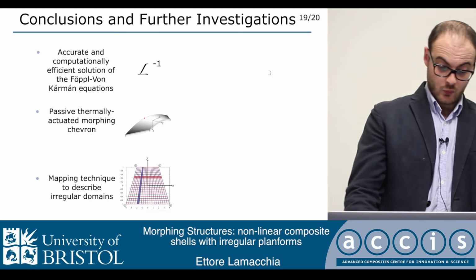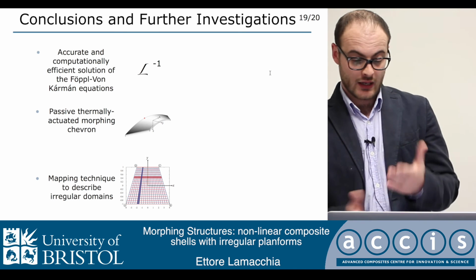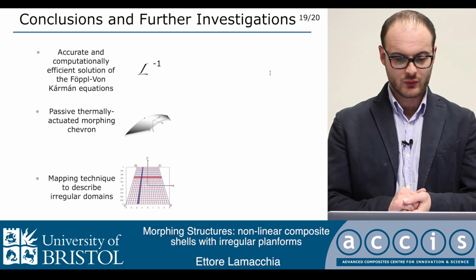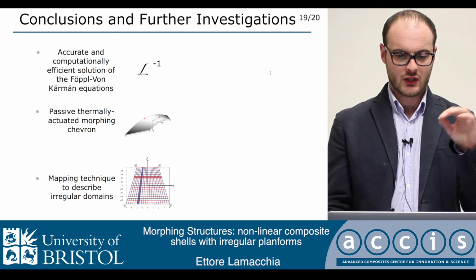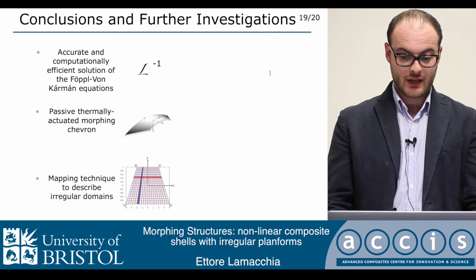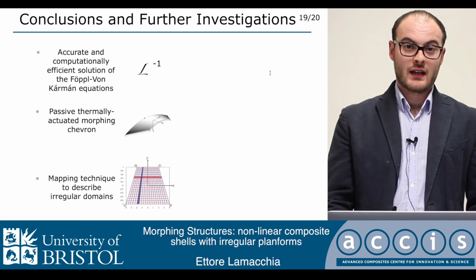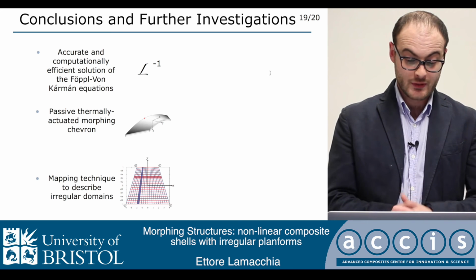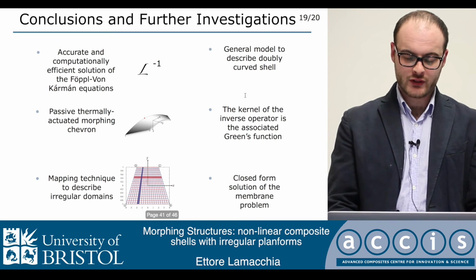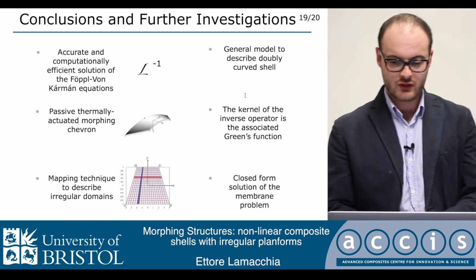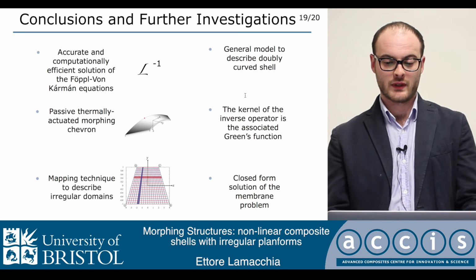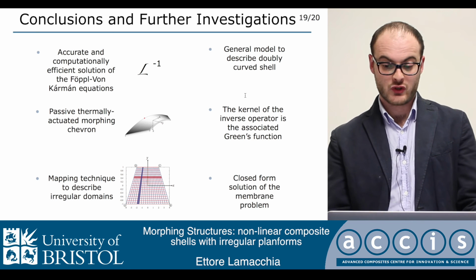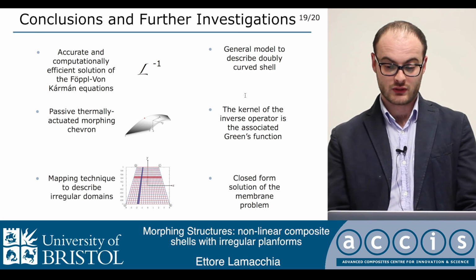So to conclude, we propose an accurate and efficient computational model in order to describe the multistability of thin composite shells with irregular planforms. We apply our model generalizing the governing equations to deal with non-regular planforms. And further investigation will look at generalizing our model to deal with general doubly curved shells with any initial curvatures.